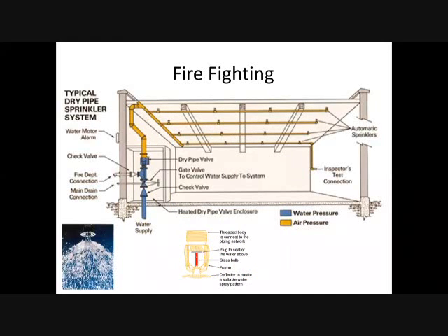This is another system of what we call sprinkler systems. Here, all these pipes must be pressurized all the time, because when a fire happens here, the bulb will explode and the water will start to come out, as you see in the picture below. So the water will come from these sprinkler heads, and it has to be controlled and under pressure all the time.